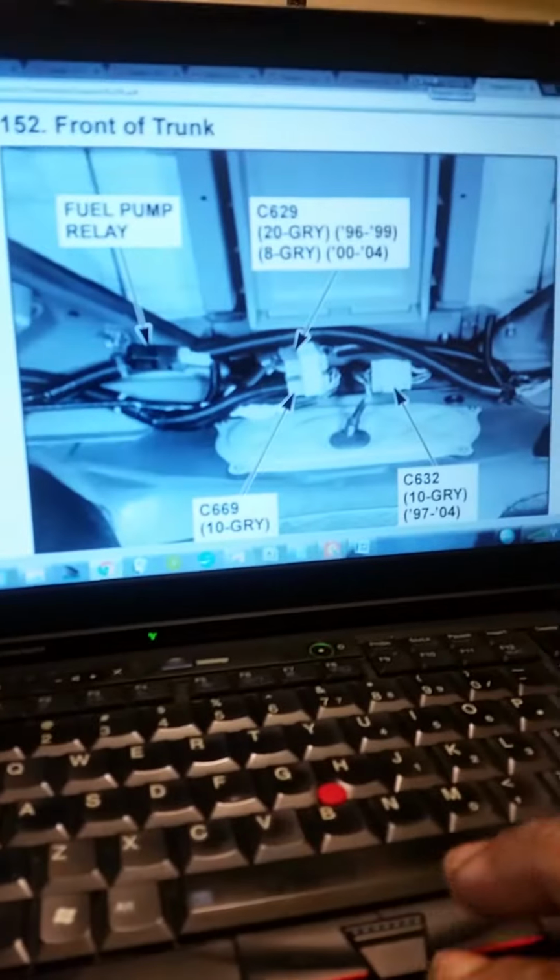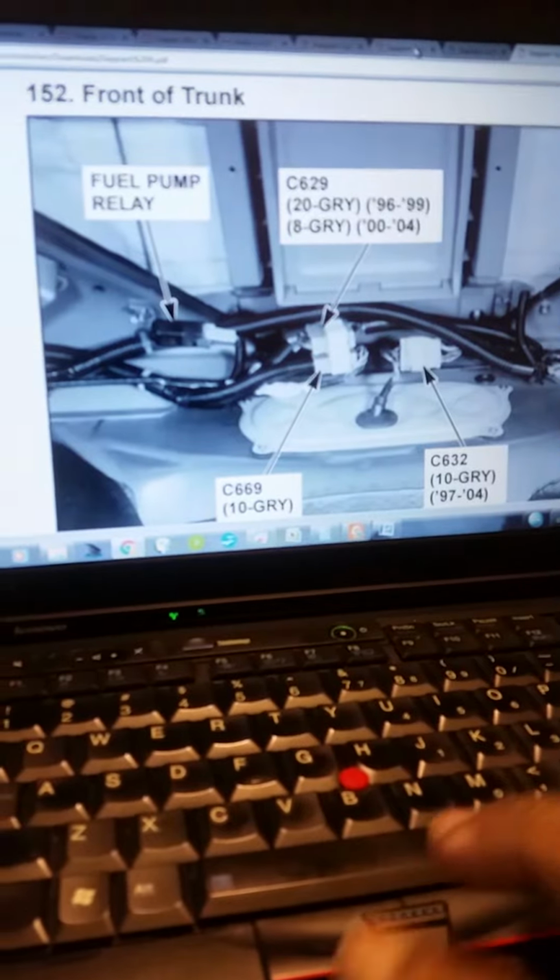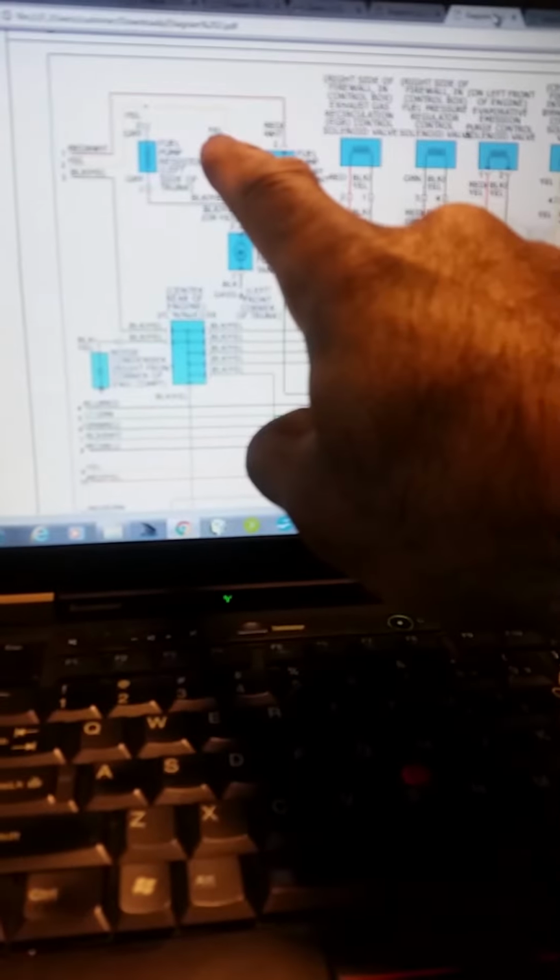All right. Turn the key off. All right, here we go. So if I didn't have power there, so this is where we were. So there's power here, and if I go back, I do believe they come from the same fuse. So fuse 20.